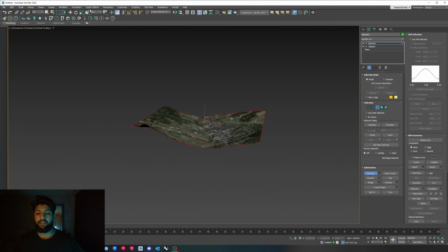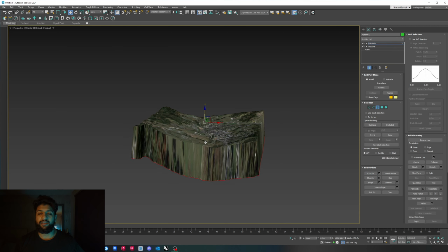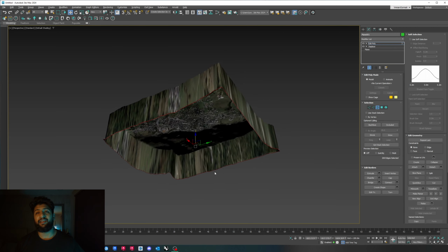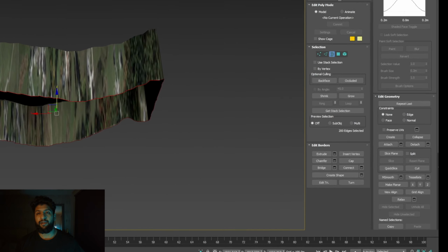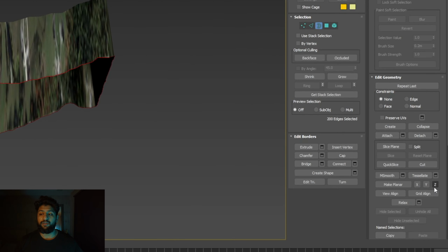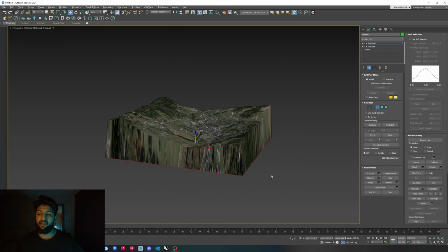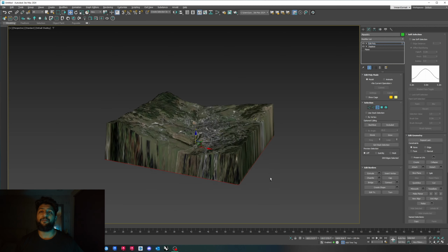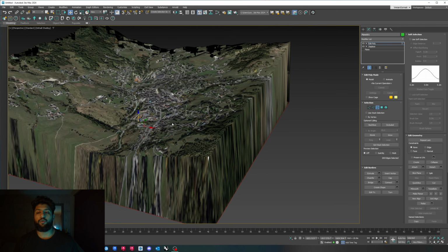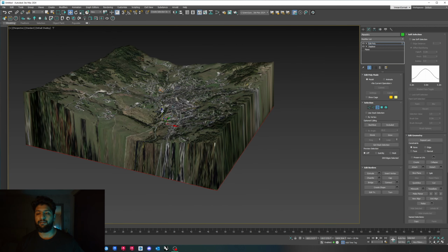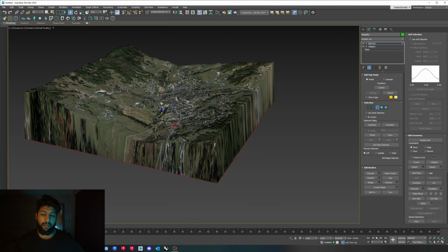There is a shortcut for the extrude on our properties bar. If you select the move tool, you can drag down your z-axis and you'll see it extrude just the border. The plane, we want it flat. So on the right toolbar, we have this button, make planar. You want to hit the Z just to the right of it and that will flatten our border so that it is all flat in the z-axis. Now you can move this up and down, make sure you're happy.